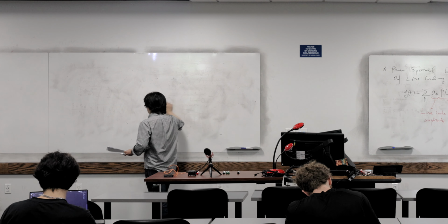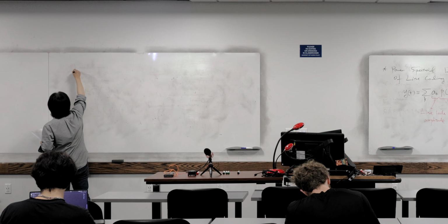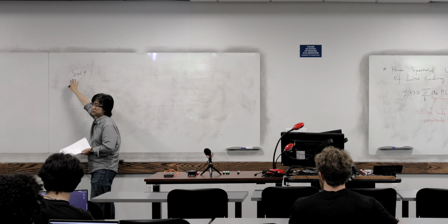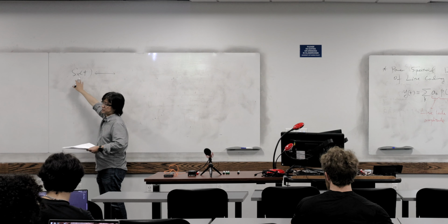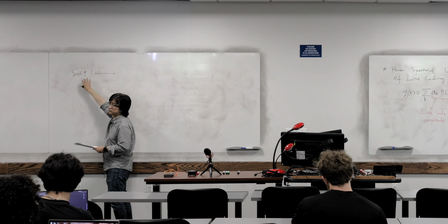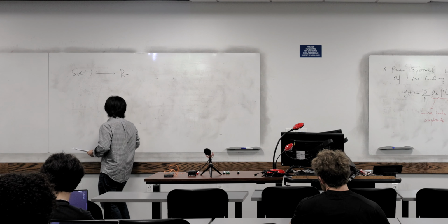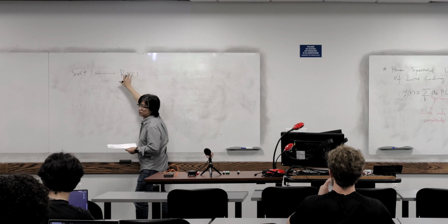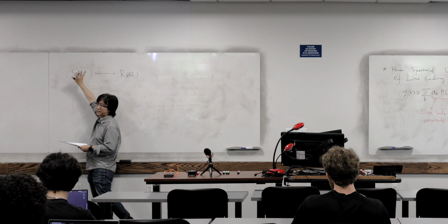We covered how to compute the power spectral density already. So how can we compute the power spectral density of x of f? We said computing that in the power domain is very hard. If you forgot, just take a look at our notes. The reason is the definition of it. What we can do is this: the inverse Fourier transform of it is the autocorrelation function of x, R_x(tau). This is not so hard to compute. If we compute this and then do the Fourier transform, we can get that.